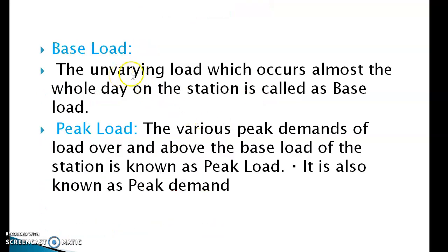First, base load. The varying load which occurs almost the whole day on the station is called base load. Peak load. The various peak demands of load over and above the base load of the station is known as peak load. It is also known as peak demand.